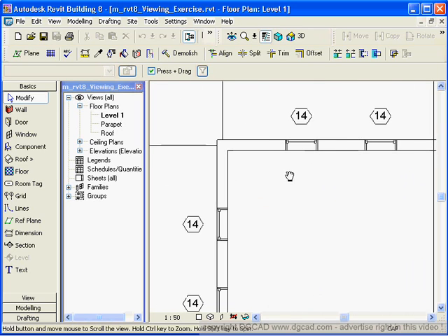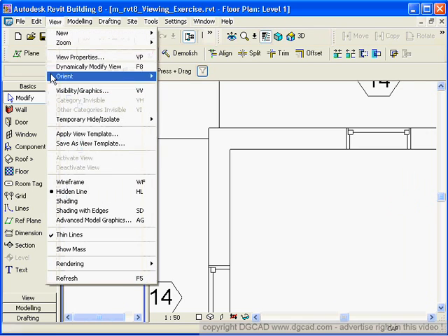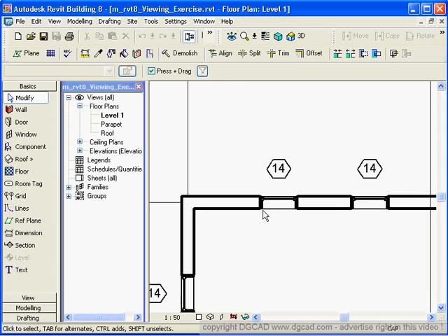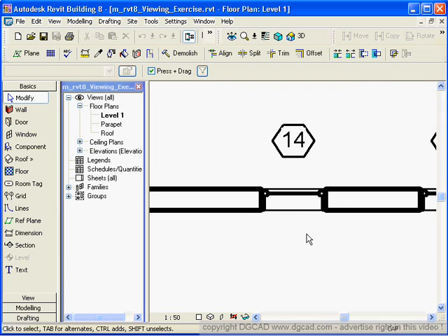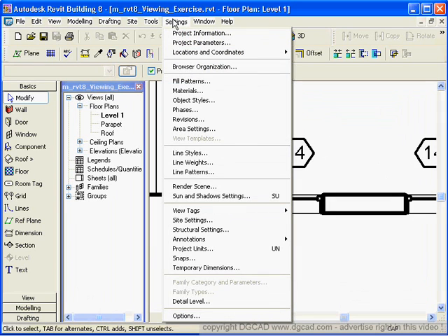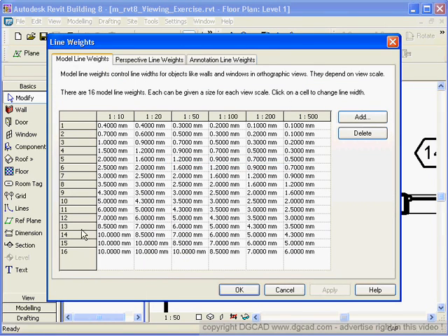So when we're talking about walls and visibility, we can go inside of here now, and right now I think what is called thin lines is turned on. If I take thin lines off, what happens is that it'll be printed as in what you see is what you get. So that will be the actual line weights, and the specifics of line weights are under settings. Under line weights, think of it as having 16 different pen numbers, and then each scale that you set down in here, this pen number will be this wide. And you can add one in and you can change these.